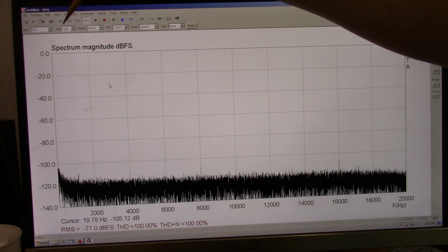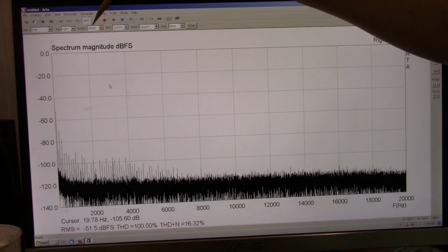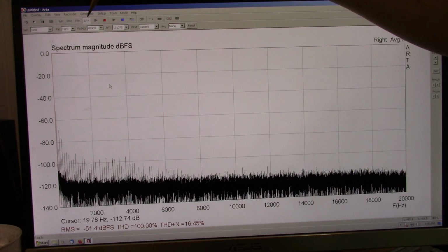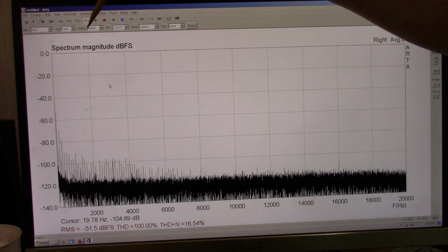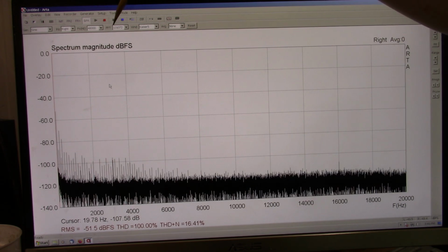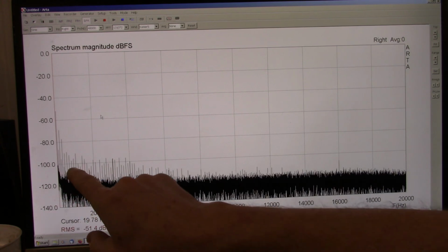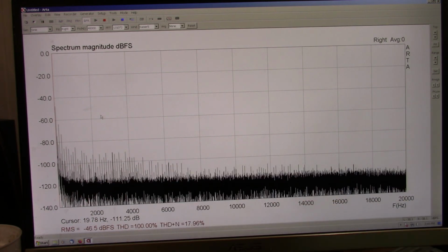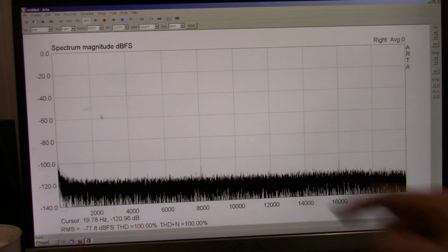But anyhow, you can only use one channel at a time, so we're using the right channel. This frequency here is the sampling rate, and it's set for 48000 right now, and I'll explain the differences, why I'm using this right now. And this is the amount of data in the FFT window. You see, my music player turned off and I'm getting noise. Let me turn it back on, because the output goes high impedance and it just lets noise in. So I turn that on and it goes away.